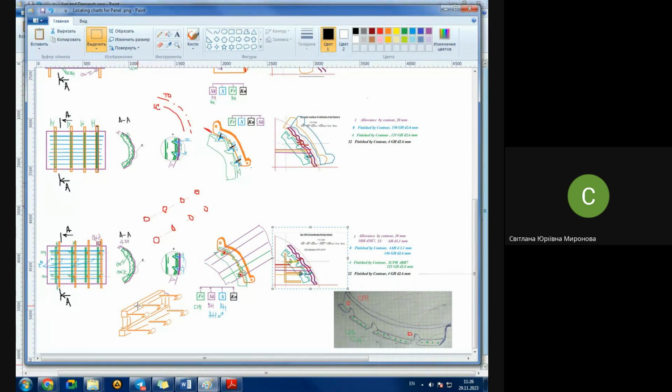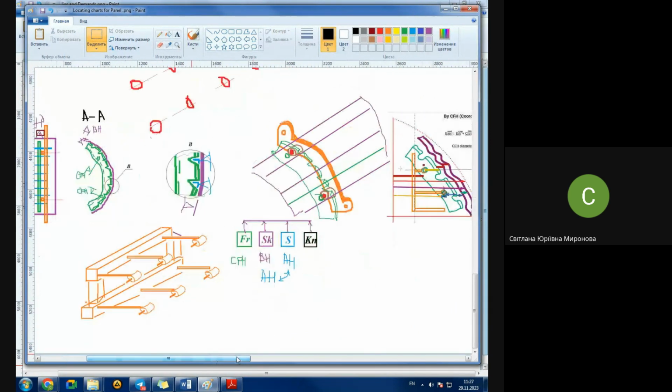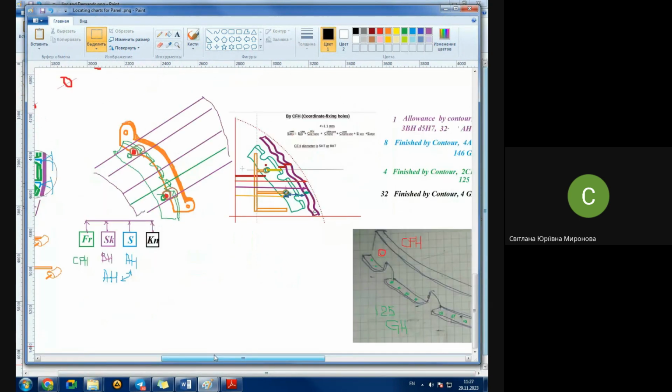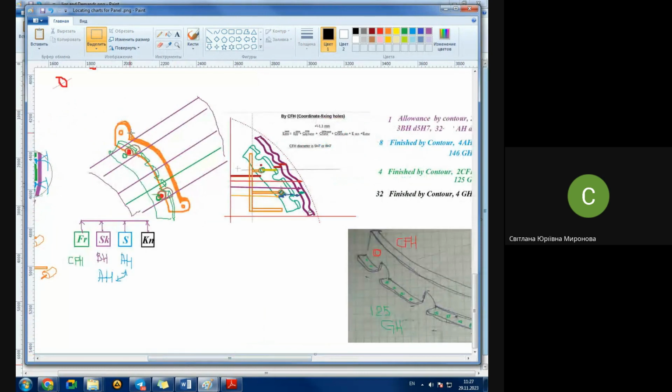And as you see at the bottom, some truss-like structure with bushings. Or they might be designed more similar to panel locators, and they are under the skin, I hope you do remember. Each such locator has two bushings, or as many bushings as you need for each frame. In our list of demands, we wrote that each frame, the green one, has two coordinate fixing poles. That is why each such folder of locators has two locators of CFH.